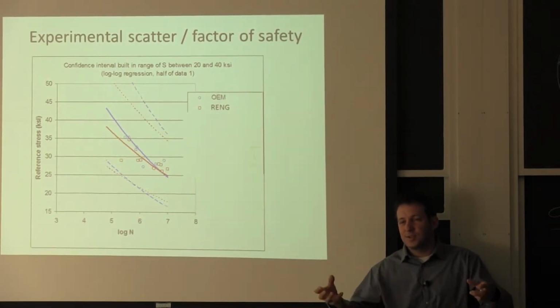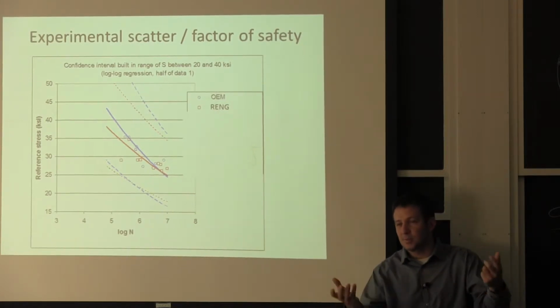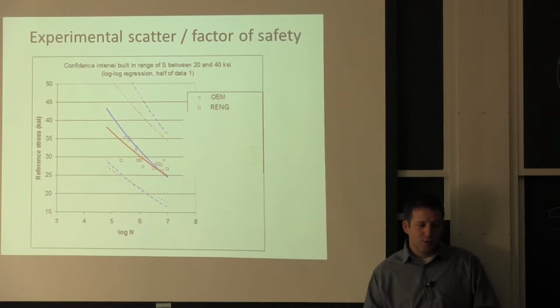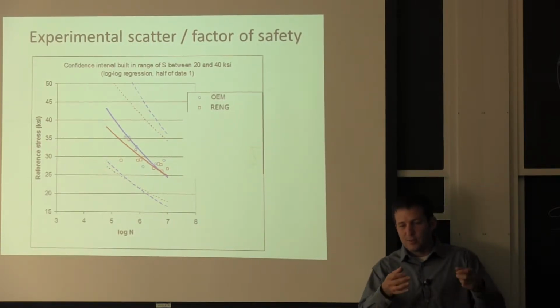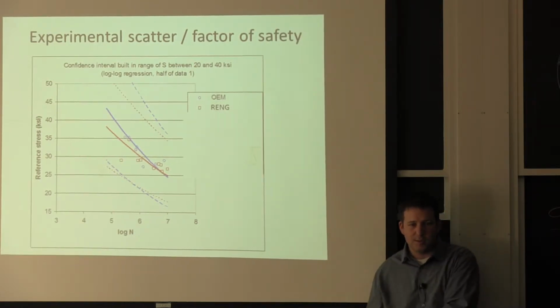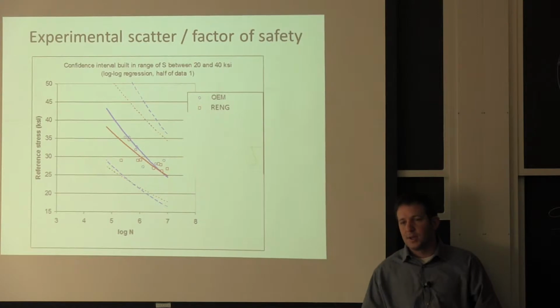Obviously, if you have 1,000, chances are you're going to have two next to each other, so that makes a bigger one. But here the idea is you're looking at a large volume of material, and the biggest impurity on one sample is going to be different than the biggest impurity in the next sample. Because these are outliers. They're things that you'd like to avoid, you just can't.